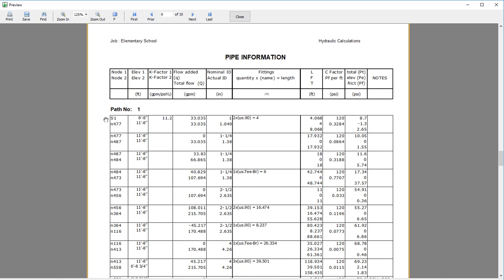In our case, we're going from sprinkler number 1, which is 1-inch pipe, for a distance of 4 feet length and a fitting length of 4 feet, which is our two 90-degree elbows, two US 90s, totaling 4 feet of friction loss, or 4 feet of additional length, for a total length of 8 theoretical feet of piping.